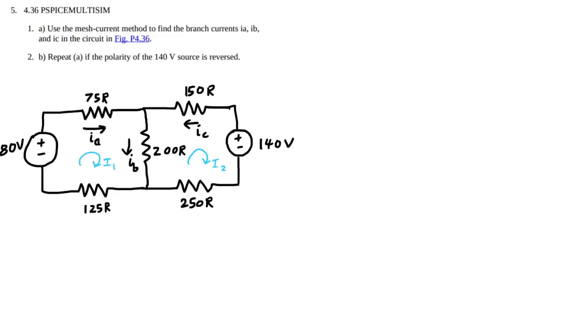You could even have one of them go the opposite direction if you wanted to. It would just make it a little bit harder to keep track. So anyway, it all centers on Kirchhoff's voltage law and these little currents. We consider a closed loop with this one current inside of it and compare them between the two.